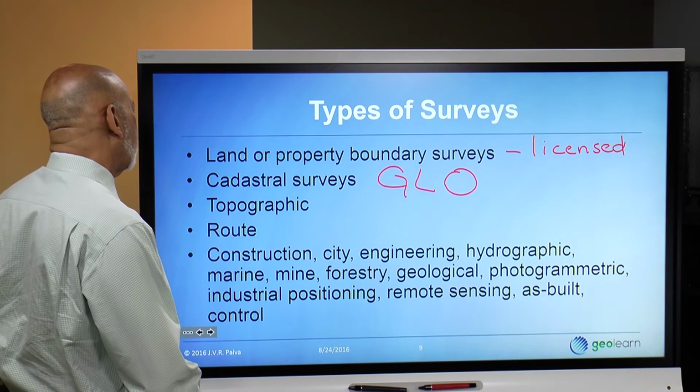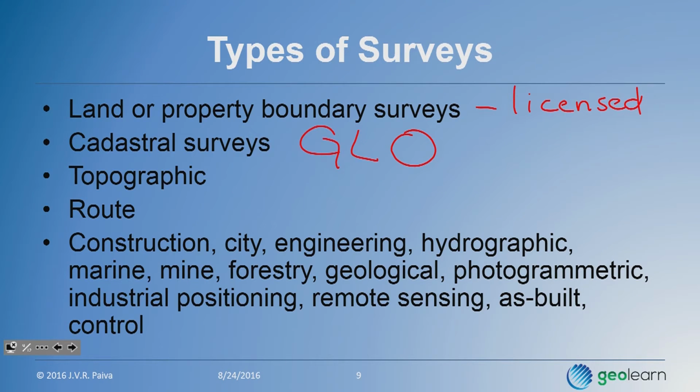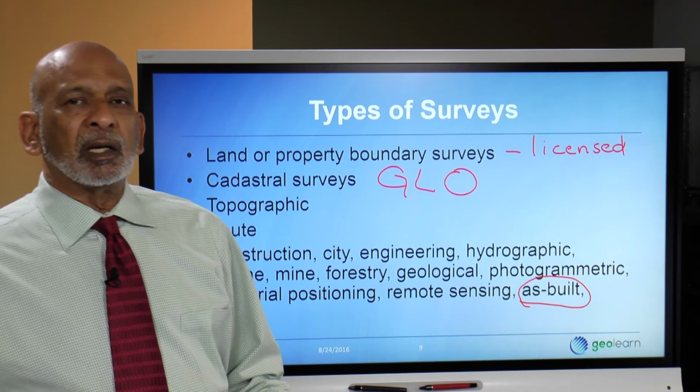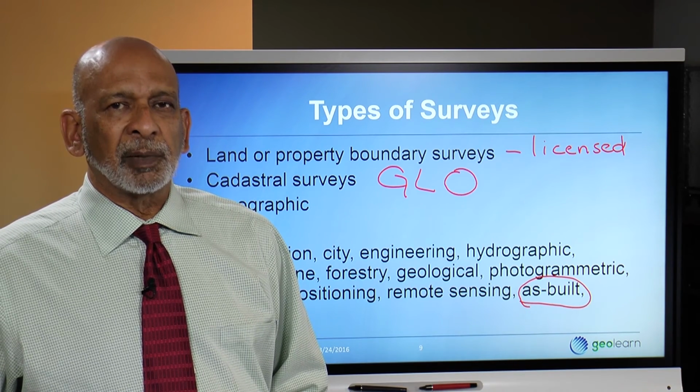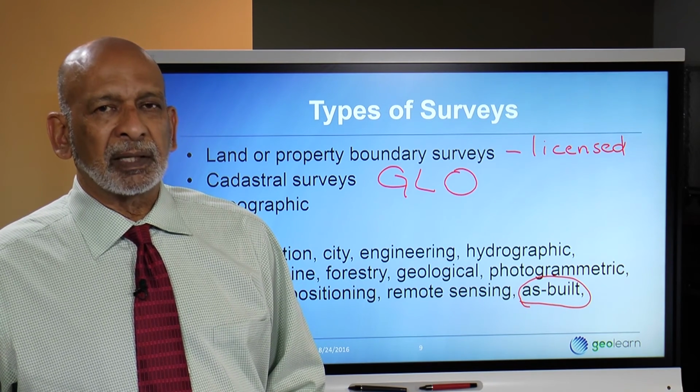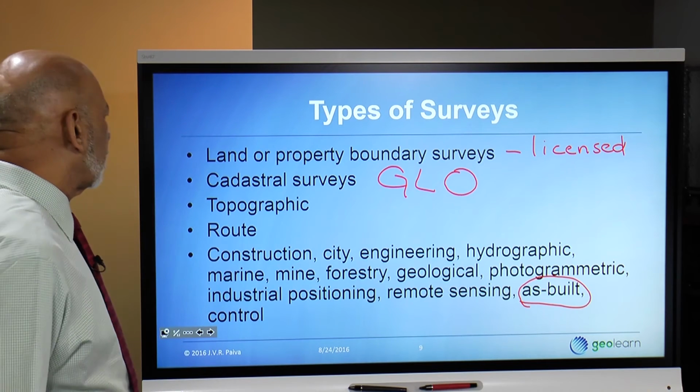Construction surveying is surveying that's done preparatory to construction and during construction. And sometimes construction surveying also includes, you see over here, as-built surveying. Sometimes that's collapsed into construction surveying as well, because if a project is done well, it really should require an as-built survey, because seldom are projects built exactly to plan.